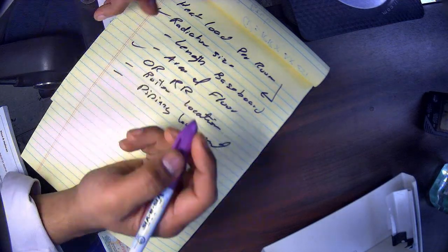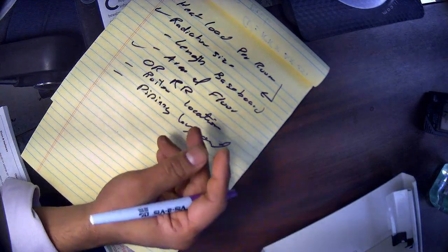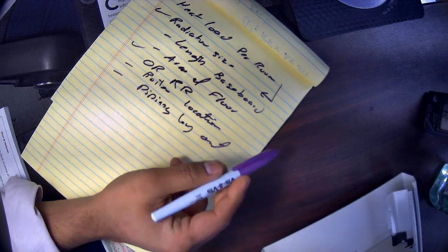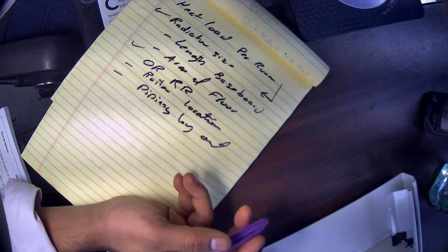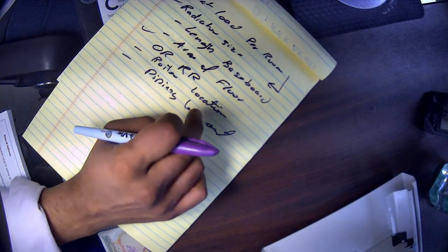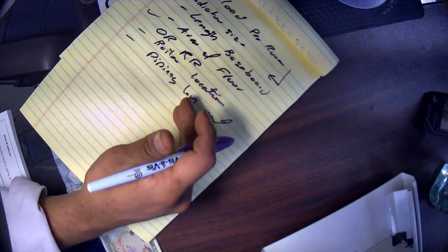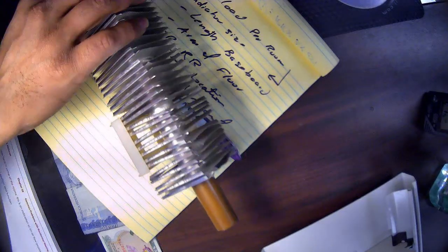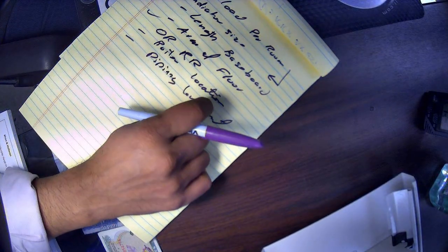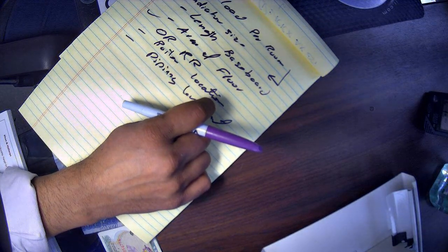Just think about it a little bit. It's good to print out the floor plan and go with a pencil and see how you are going to lay the pipes and how much radiation do you need, and just put it with a pencil and see if that makes sense to you or not. The issue that I want you to think about is that why, because some rooms require a lot of heat supply, and if you're going to run like 20 feet of these, it's not going to be a good design. You don't want to be in a living room where all around is just baseboard radiators. That doesn't seem like a very good, probable design.